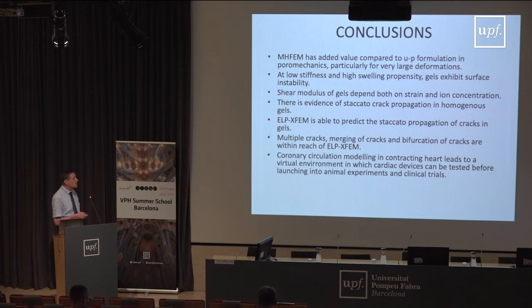Shear modulus of gels depends both on strain and ionic concentration. There is evidence of staccato crack propagation in homogeneous gels, and the XFEM method that we developed is able to predict the staccato propagation of cracks in gels.